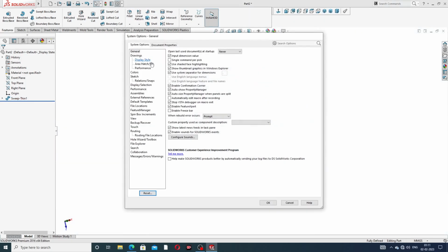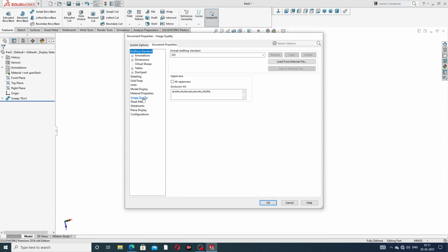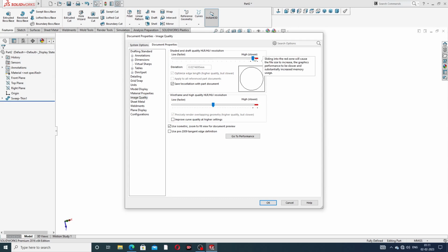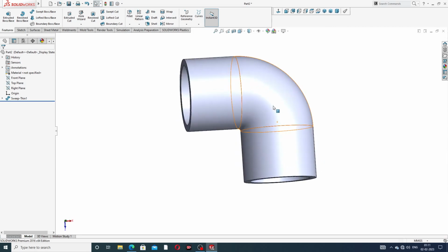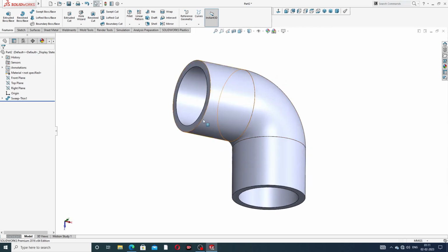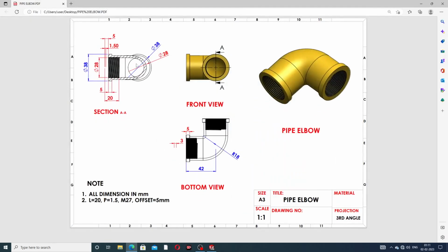Okay, and page select here, image quality is very high. Okay, this is perfect, this point is correct. And next is drawing here, some boundary, and this thickness is 5 millimeter, with inward direction. A circle is drawn here, this is 38 millimeter, and all values are correct.